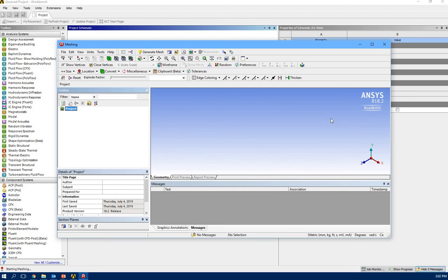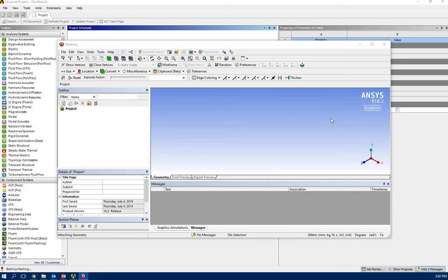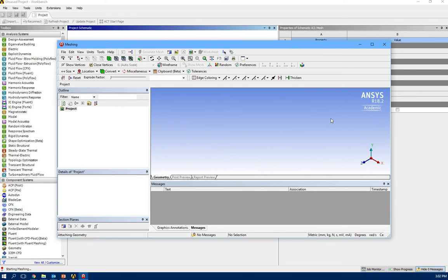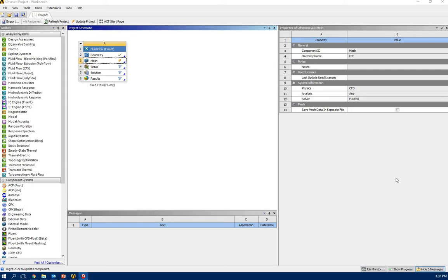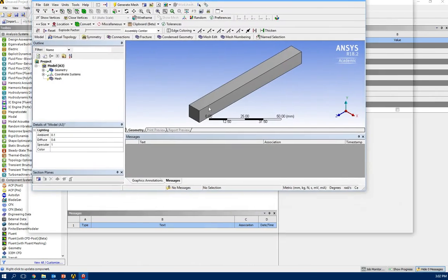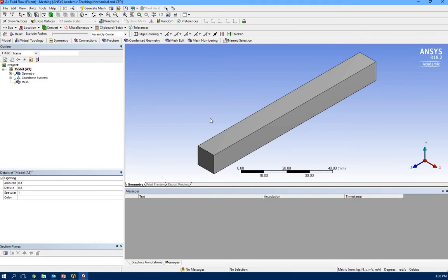For example, here we have a long 100 millimeter bar, and we want to find temperature. So one solution would be to find temperature, for example, for 100 and 1000 points over that geometry. Or we can say, let's simplify it. Let's divide that geometry to smaller versions and solve those discrete selected areas, and then use those.